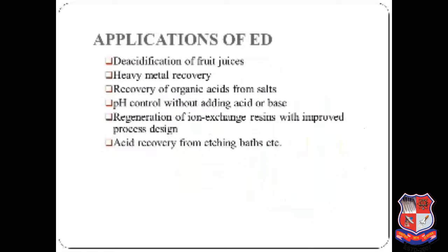Electrodialysis processes are different compared to distillation techniques and other membrane based processes in that dissolved species are moved away from the feed stream, rather than the reverse as in reverse osmosis. Because the quantity of dissolved species in the feed stream is far less than that of the fluid, electrodialysis offers the particular advantage of much higher feed recovery in many applications.